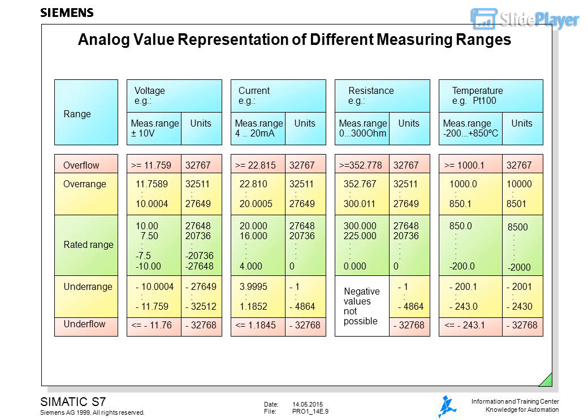Voltage, current: encoding the symmetrical voltage or current ranges. Symmetrical: plus or minus 80 millivolts, plus or minus 2.5 V, plus or minus 3.2 milliamperes, plus or minus 250 millivolts, plus or minus 5 volts, plus or minus 10 milliamperes, plus or minus 500 millivolts, plus or minus 10 volts, plus or minus 20 milliamperes, plus or minus 1 V. Results in a rated range of minus 27,648 to plus 27,648.